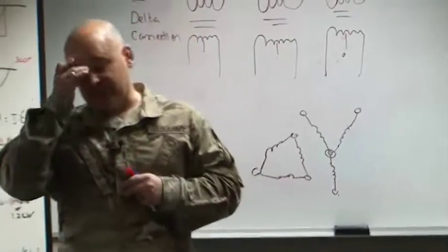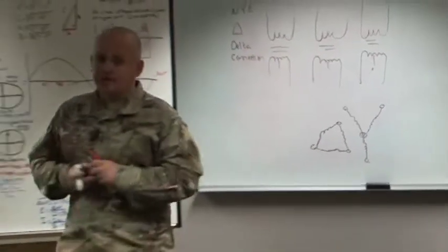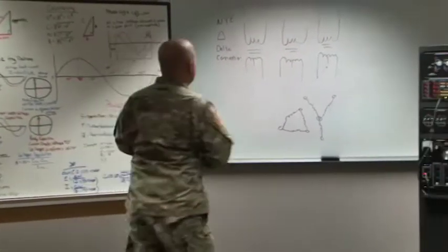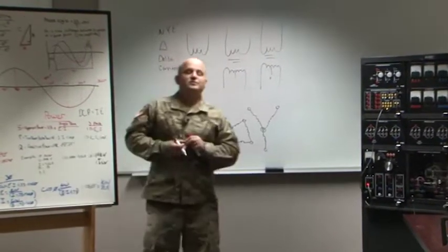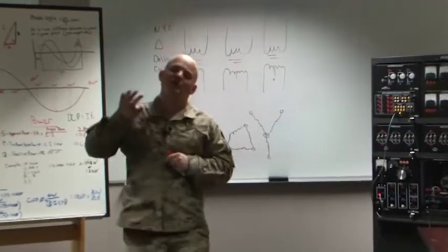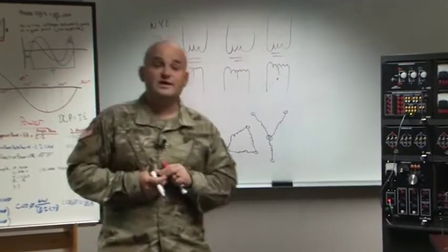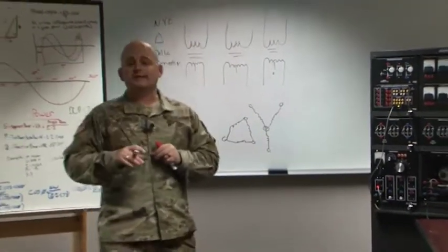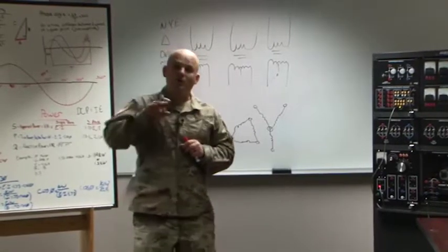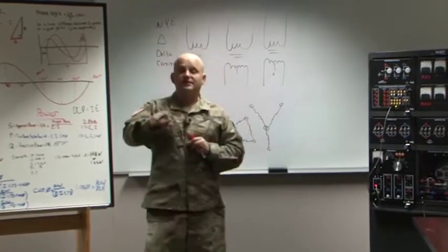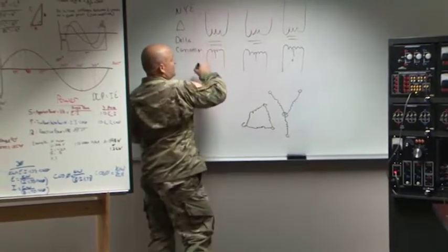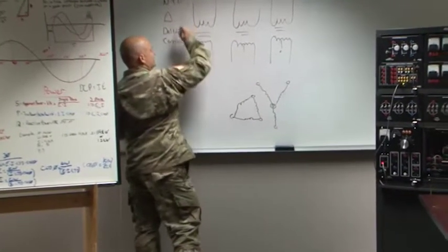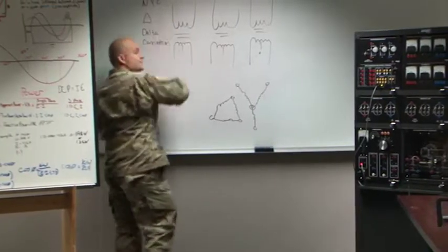This same principle applies to the transformers as well. With transformers, though, we're now referencing both the primary side and the secondary side. So what does that mean? That means we're going to talk about four specific connection types with three-phase transformers. Those four connections are Y-Y, Y-delta, delta-delta, and delta-Y. You kind of pick it up, right? Y connection, delta connection, delta connection, Y connection.